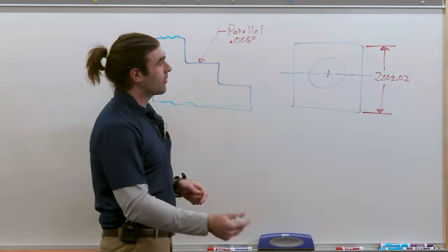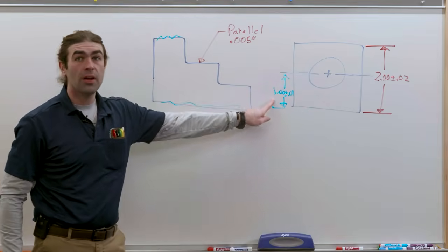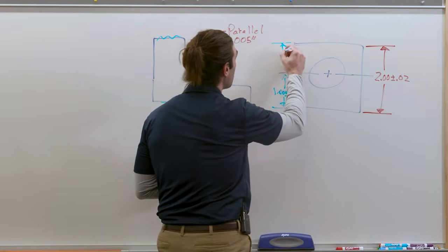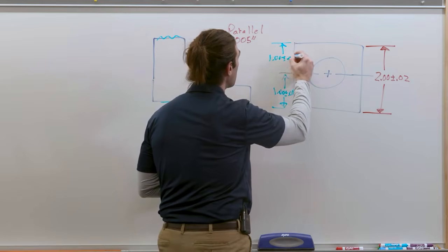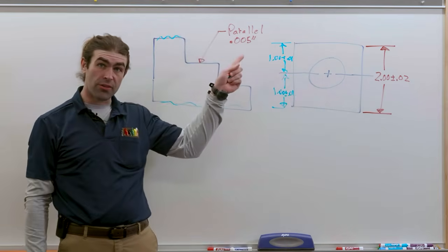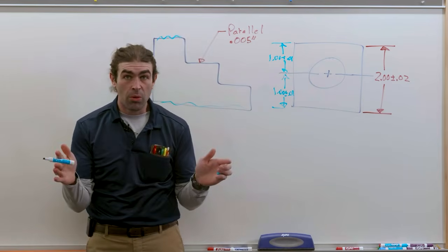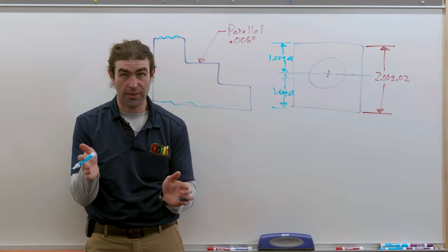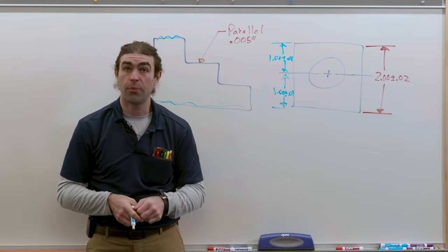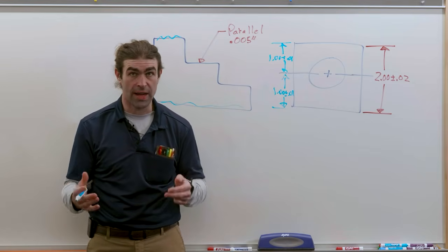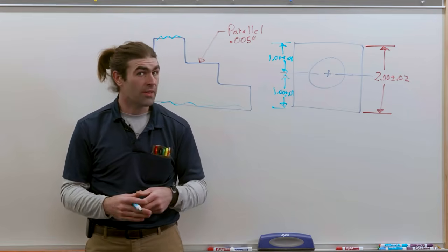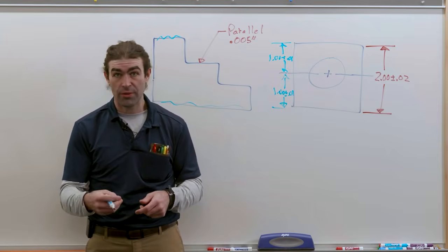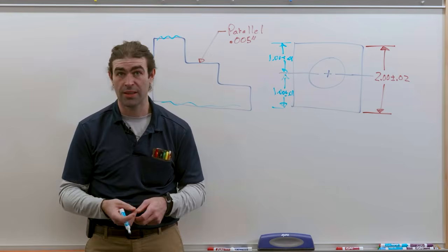But one person could say, let's measure from this surface, make it 1 inch plus or minus 10 thousandths. Another person might say 1 inch plus or minus 10 thousandths from that surface. Another person might say, well, why don't we take the block and put it in a vise and then find the center, right? Simulate that center line and then get the location from there. Now, none of them are really correct, right? Plus or minus dimensioning really doesn't have rules for how to do this stuff. You're leaving the interpretation up to whoever has the drawing, who's making the part, who's inspecting the part.